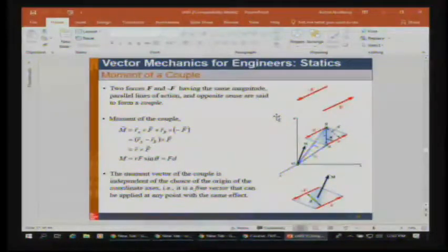So in other words, it's two forces of the same magnitude pointing in the opposite direction, separated by some distance. Now, the physical importance of a couple is, if you have an object being acted upon by a couple, the summation of forces in the vector directions due to the couple are equal to 0, and yet there is a tendency to a rotation. So a couple will have that tendency to produce a rotation without moving it in a linear manner, or in a translation.